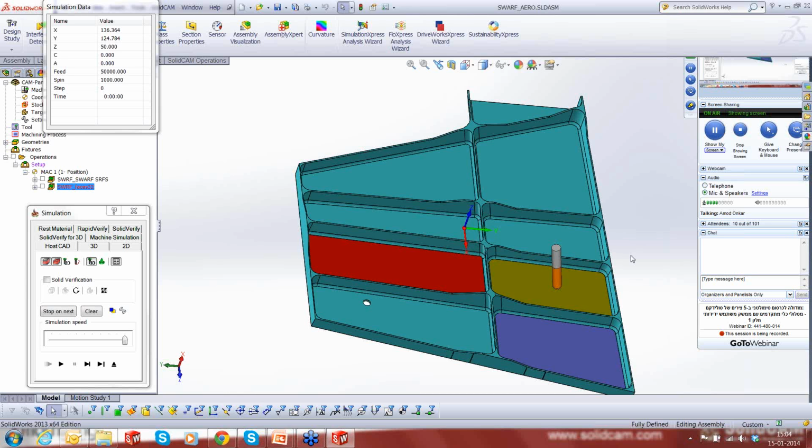You could also use swarfing as a finishing tool for finishing the sides of an impeller with a cross section in a straight line. You could just do one pass around the entire periphery of the impeller and have your finishing done instead of giving multiple passes to it. So straight away, I have two applications where swarfing can be of great help to the user.